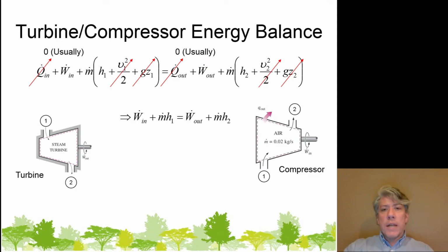What about turbines and compressors? Well, with the turbine and compressor, usually there's not enough heat interaction to worry about. Sometimes there is, but usually there's not. The kinetic and potential energy changes are also usually negligible, and so we end up with an interaction between work and enthalpy.